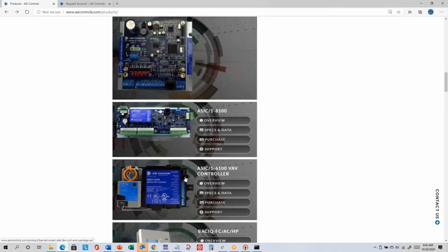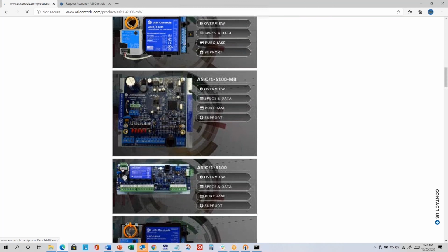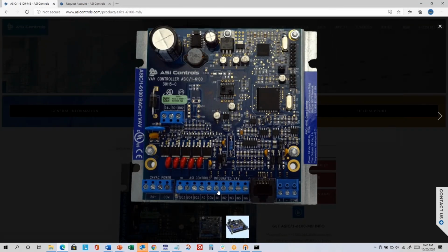And so let's go back to the metal-based one so we can see the circuit board a little better. It's there. And so this looks like an Ethernet. Actually, there's an analog output, 0 to 10 volt DC, and then there's a single common, and it's connected to ground, and it can be used for both the analog output and the inputs. There's only one common connection just because we don't have a lot of board space here.